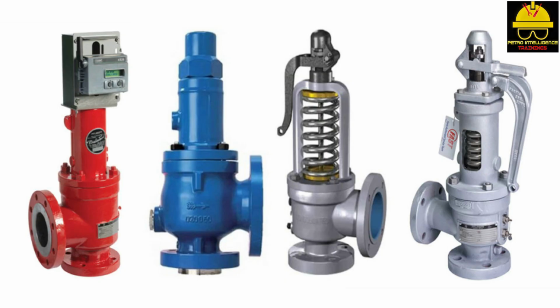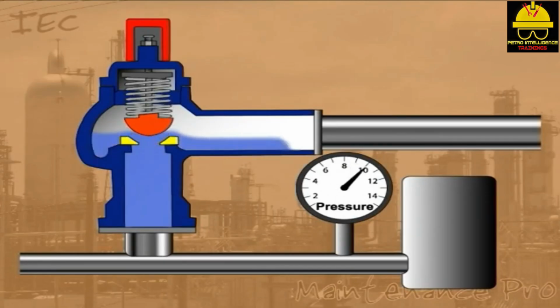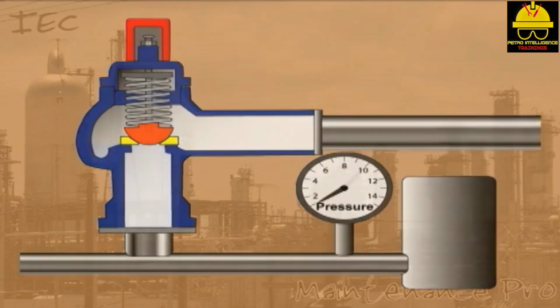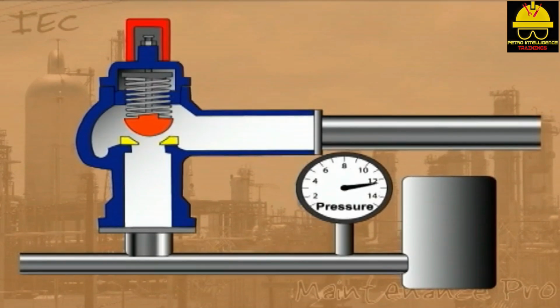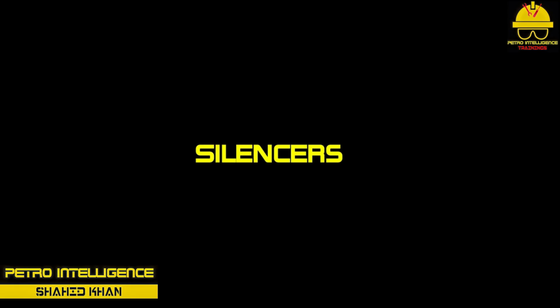Safety valves. Safety valves and pressure relief valves are used to relieve excess pressure that could damage operating equipment and hurt operating personnel. These valves are sized to handle specific flow rates and should not be replaced without ensuring that the replacement valves meet engineering specifications. Some safety valves automatically reset. Other types must be removed and mechanically reset.